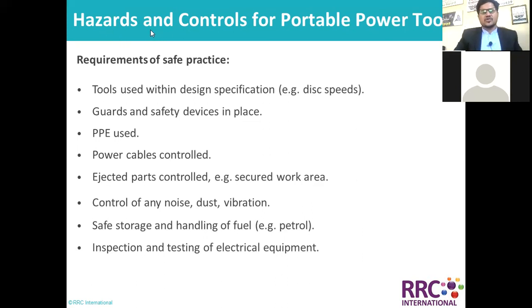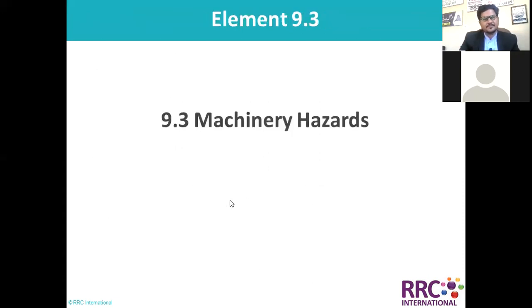Now, hazards and controls for portable power tools, we can still discuss some of the requirements for safe practice. Tools used within the design specification, like disk speeds; guards and safety devices in place; PPE used; power cables controlled; ejected parts controlled and secured work area; control of noise, dust and vibration; safe storage and handling of fuel like petrol; inspection and testing of electrical equipment as well.